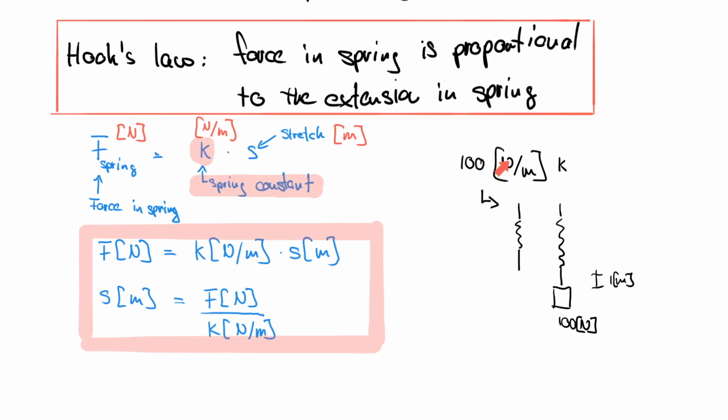So this would be a very weak spring. It would be very useless in construction or for structural engineers, but the concept applies. Whatever number you have, that's how much it takes to stretch it by 1 meter, and that is the real physical interpretation of the spring constant. In real life, you will find something like a meganewton per meter, or even larger numbers. That would then take 1 meganewton to stretch the spring by 1 meter. But this is how you read the spring constant, and that is important to understand for engineers.